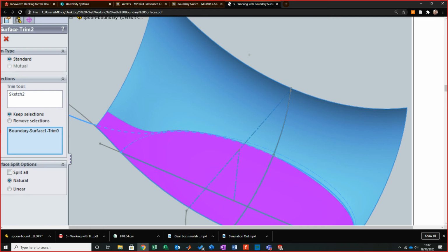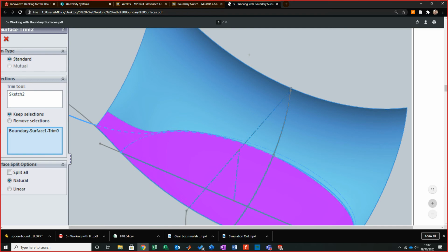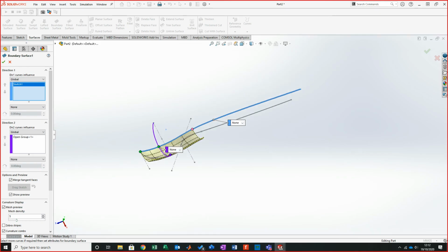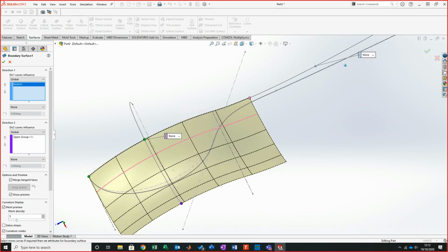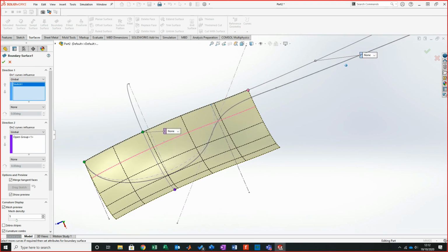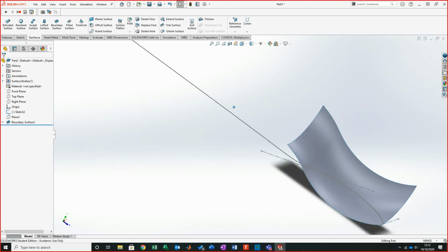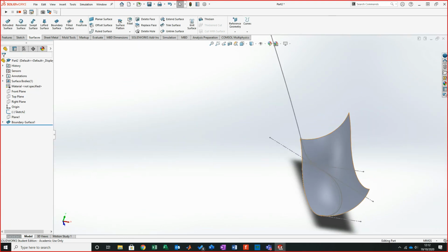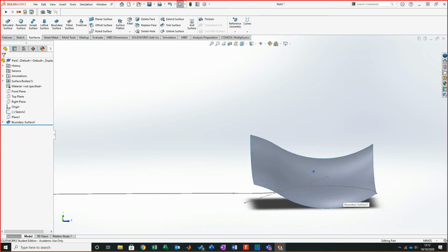It's just at where I'm necking based on my construction points. So let me come back down, zoom into the edging a little bit, and it's just about where I'm necking to that area, so that'll be okay. Right, so now what I'll do is I'm going to trim out this profile, because that's what's going to give me my initial first point of the spoon.